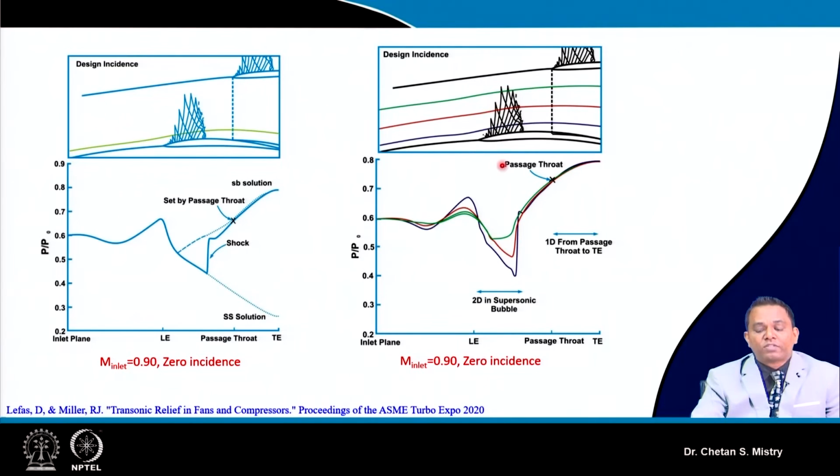Comparatively less acceleration happens for the second streamline. And the third does not come in the acceleration region, which is why it is not subjected to any kind of shock formation. This is a continuous flow in the sense of diffusion.